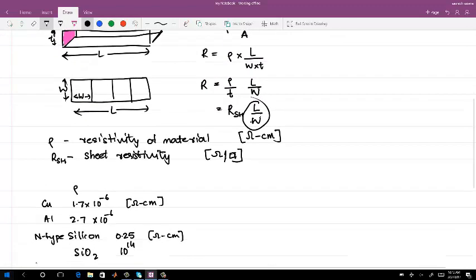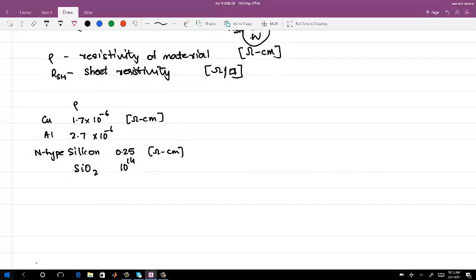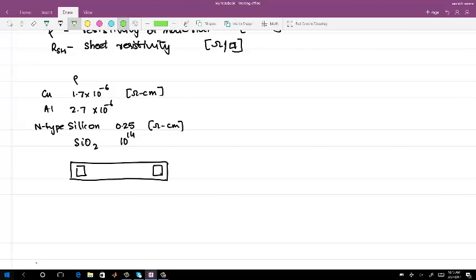So this is a passive resistance which once you fabricate, it has a finite resistance, and then depending on the process, it has a variation. When you realize this resistance on chip, there is something which is often neglected. I'm showing a top view. In order to connect to anything, you will connect through metal, so you have metal contacts on the silicon.